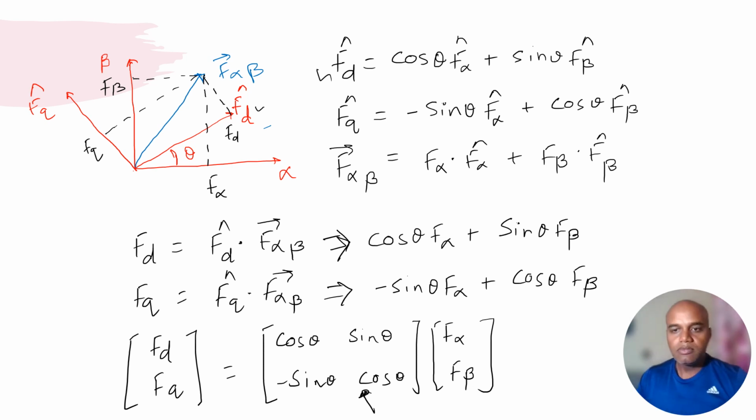In the next lecture we will see how these simulations are done through a block diagram technique. I hope now we have understood how the Clarke and Park transformations are done, and how they are helpful to convert the three-phase values into DC values, which are easy to control.